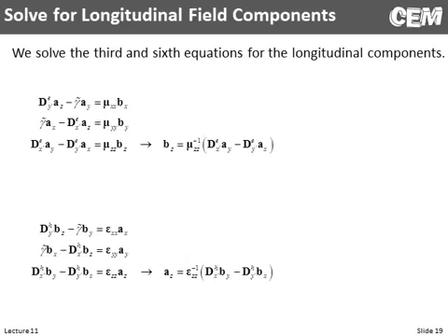Now this theme comes up very frequently in computational electromagnetics. We expand Maxwell's equations into the 6 component equations. We jump to matrix form. We solve now for the longitudinal components. We substitute that back into the remaining 4, put that in matrix form. That came up in transfer matrix method. It's going to come up here. It'll come up again in rigorous coupled wave analysis. It'll come up again in method of lines. So it's a very common manipulation.